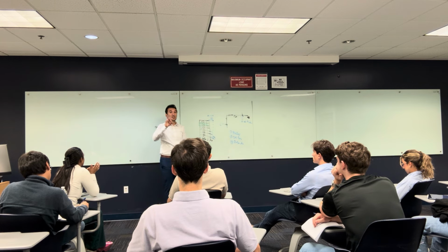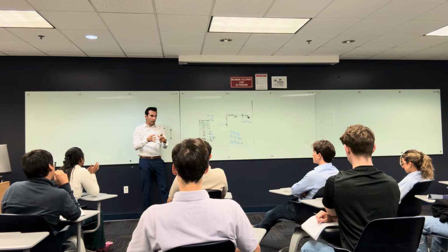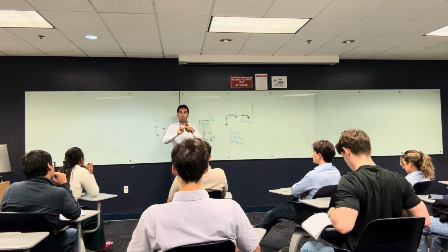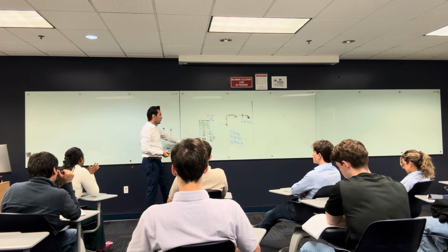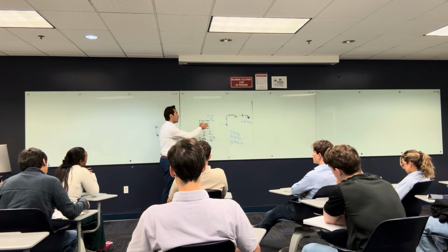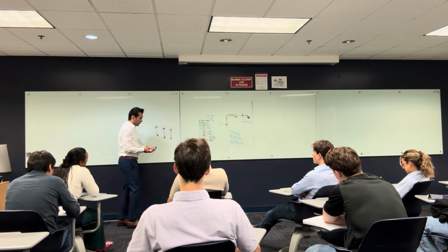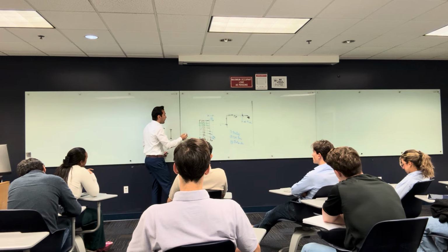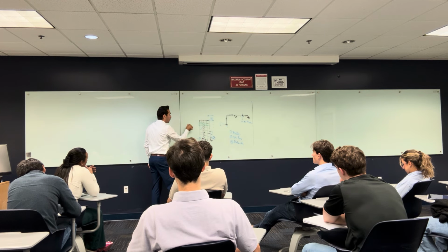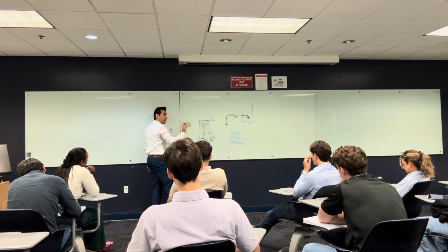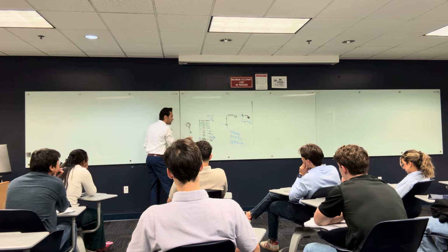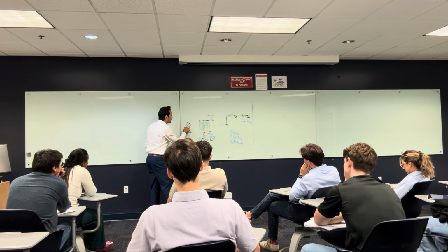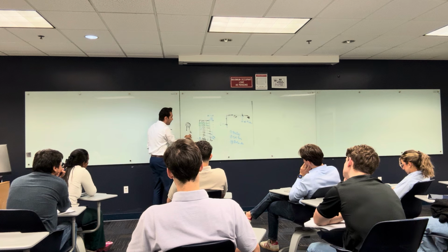So there are three components that contribute to the performance of the structure during an earthquake: the mass of the structure, the stiffness of the structure, and the damping capability of the structure. So what I need from all this is to find the deformation and the axial forces. If I were able to convert this whole structure to one equivalent mass, and convert the stiffnesses of all these columns to one stiffness K, and convert all the damping in the structure,